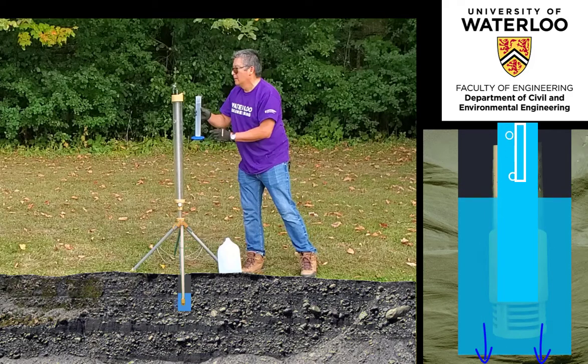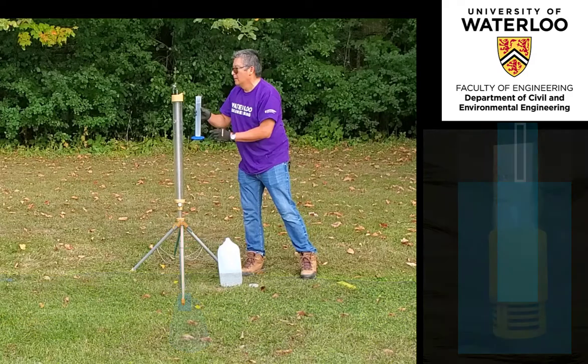Now, as the water advects from the borehole into the surrounding porous media, a zone of saturation is created and the water level in the borehole begins to decrease, creating a partial vacuum at the top of the fluid cylinder reservoir. The disequilibrium in the pressure is then corrected by air entering the reservoir in the form of bubbles from the base of the air tube, which allows the water to flow from the reservoir into the borehole while maintaining a constant head delta H. Infiltration from the permeameter into the borehole and thus into the porous media continues over the period of the test.